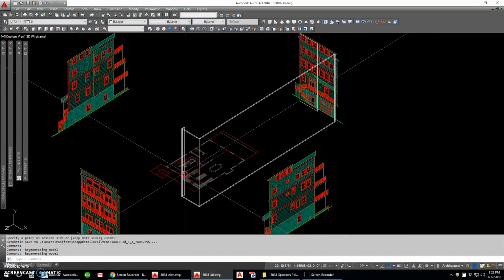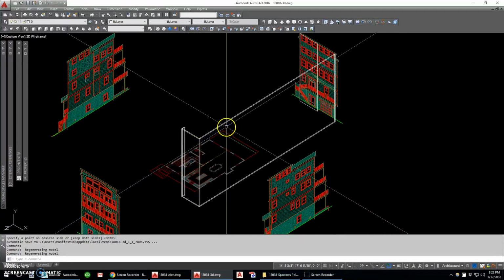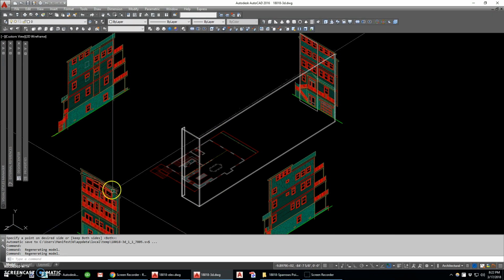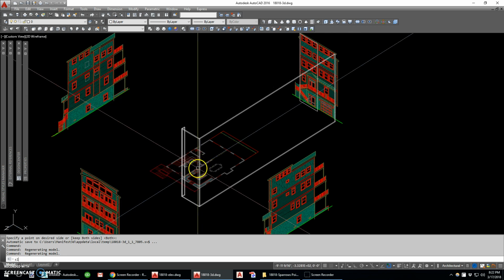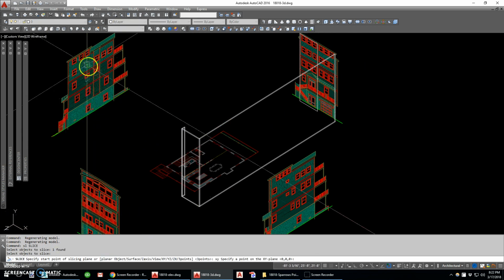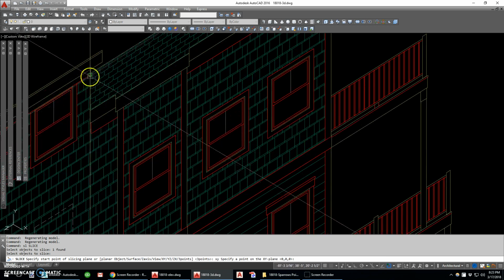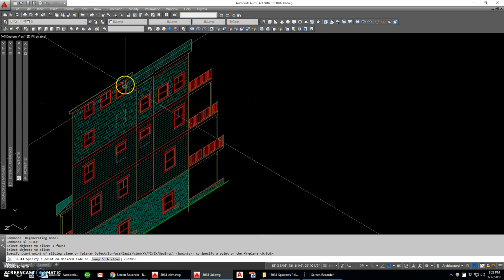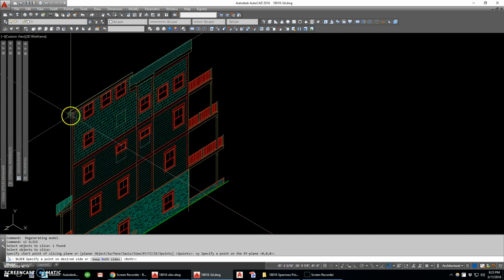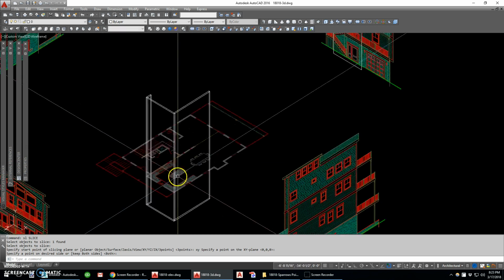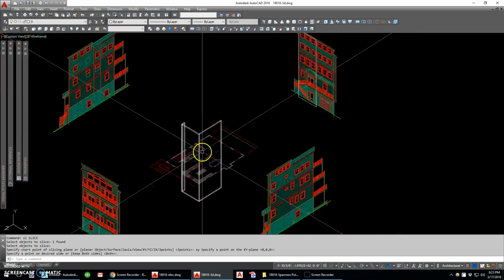As I look at the right side of this house, I see that the wall is the same going back until this point, in which, if you look at the back elevation, you've got this bump up. So I'm going to slice this wall on my XY plane at the back of this bump out. Now I don't want to hit the trim, I want to hit the wall. And it's asking which side to keep. I'm going to pick something here. And as I look back, my geometry is right.